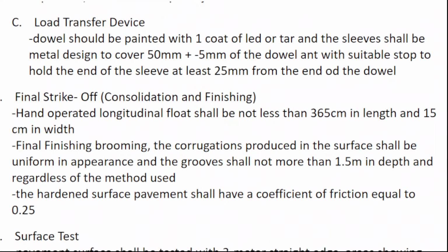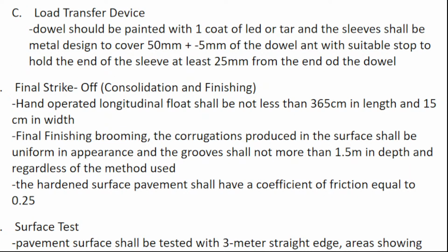Final strike off, consolidation and finishing. Hand operated longitudinal float shall not be less than 365 cm in length. So 3 meters and 3.65 meters. 15 cm meaning 150 mm in width. Final strike off. Final finishing, grooving.